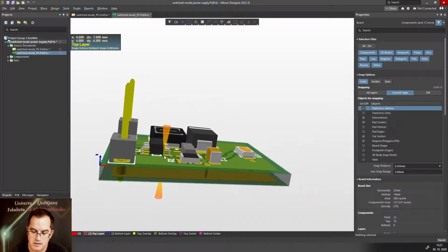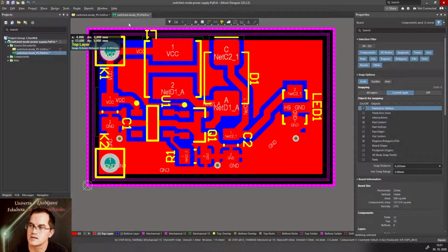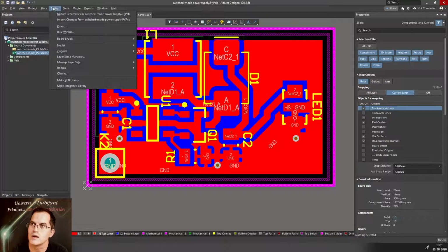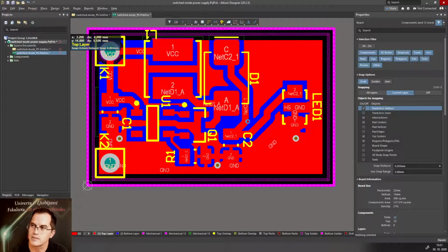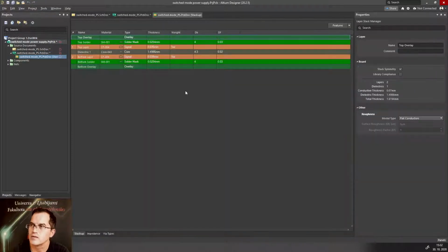And in the meantime, yes, I must say, the designer of this circuit, which I took it from, did not set correct layer stack. So we have to set it up. Maybe it was, I'm not sure right now, maybe this PCB is just too small and therefore the layer seems to be thick, but we'll check it out. Anyway, using bottom layer for return currents is very advisable.